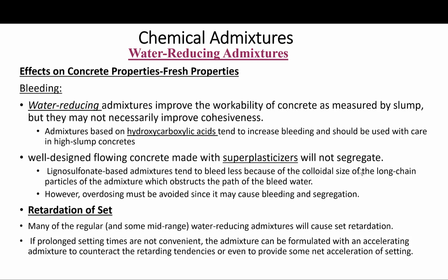So the lignosulfate-based admixtures, as I said, tend to bleed less because they entrain air. And that's one other thing here. We're talking about side effects. Any regular water-reducing admixture, regardless of its own air entraining ability, will reduce the amount of air entraining admixture required to attain a given air content if it is added at the same time only.